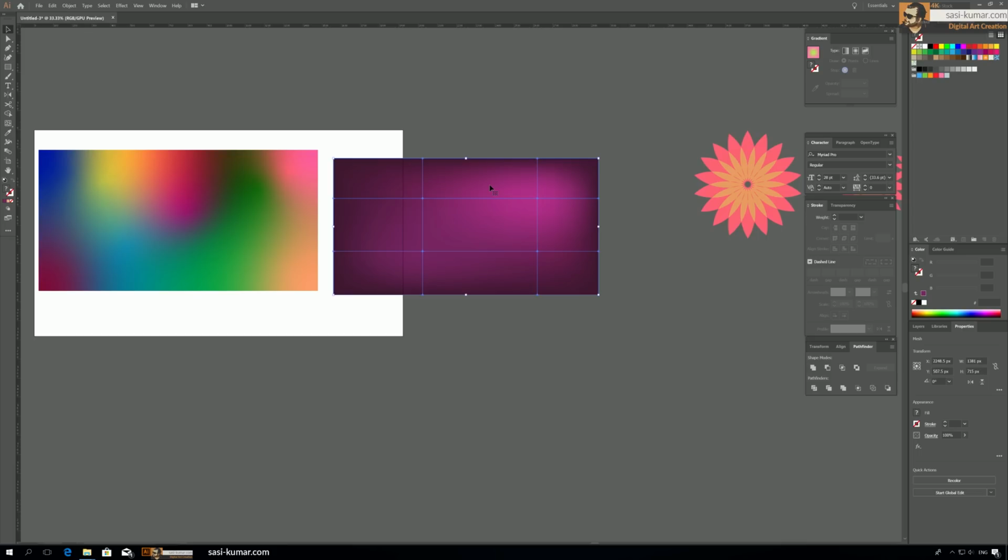You can use this, but I personally don't use this mesh tool much, because this tool is not expandable as the other gradient. So for example, if you use mesh tools, you won't be able to export these things to some of the software which you may need for production. Also, let's say if you want to sell stock pictures, vector pictures to Shutterstock or others, if you use the mesh tool, it's very difficult for you to export it the way Shutterstock or the other application wants. So when you use this mesh tool, be careful. I don't have anything against the mesh tool, but just be careful, because a lot of applications won't support the mesh tool, because it's one of the oldest tools available in Illustrator, I think. All right, guys. So let's delete these two.